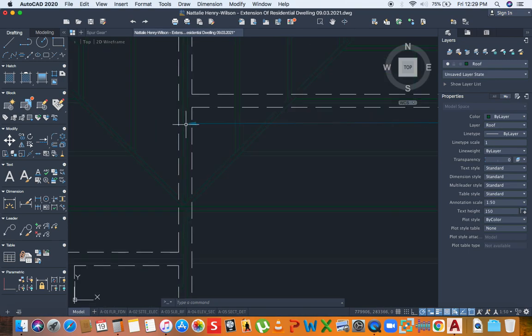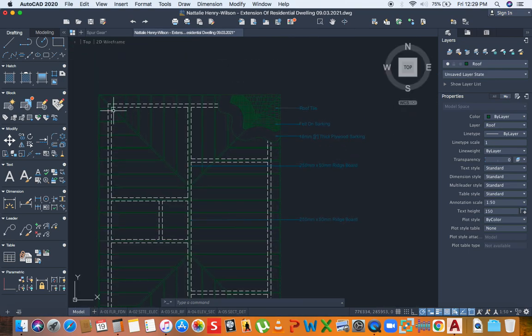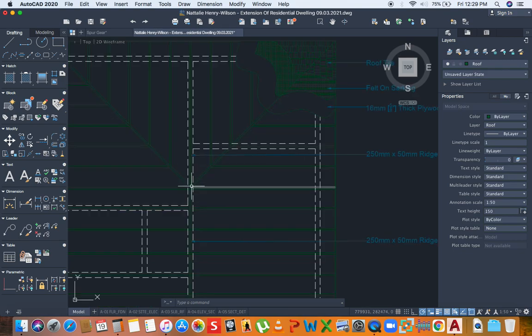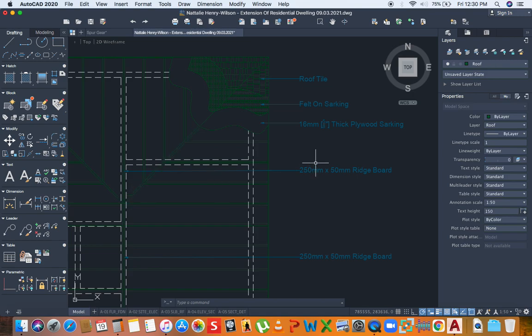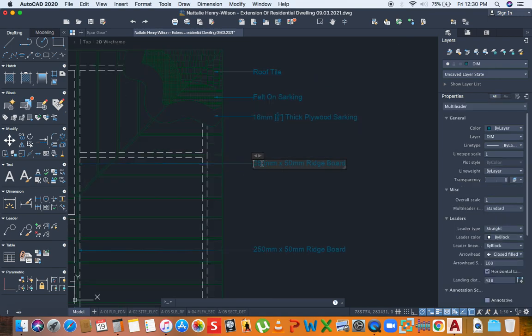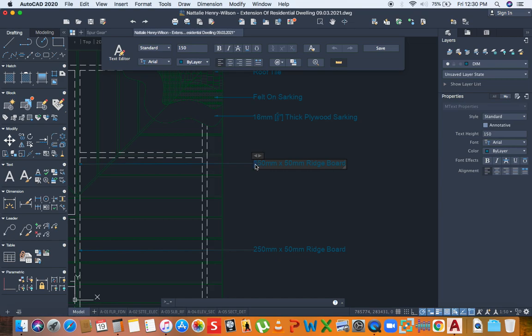And this member right here is a crown rafter. The crown rafter, if you notice, there's a triangle forming here. The crown rafter is a rafter that sits between two hip rafters. So it's 45 degrees to the hip rafters, to two adjacent hip rafters. And it spans from the fascia board here, or the eave. The eave is the overhang, to the top of the roof, to the ridge board. And the size of this, 150, and the width is the same. So you call this crown rafter.